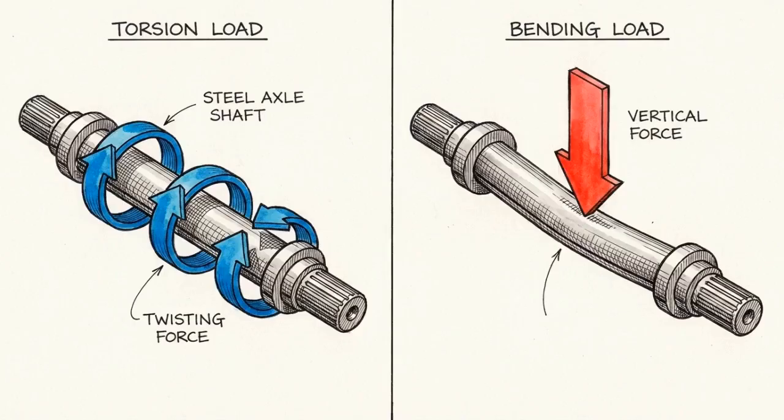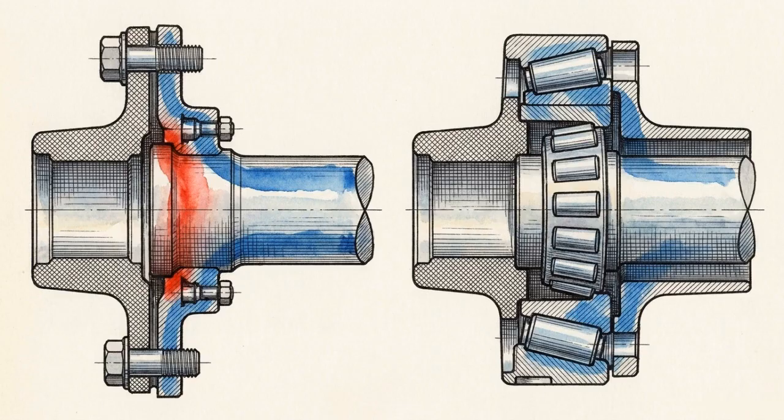The axle shafts must now carry this multiplied, balanced torque outward to the wheels, while the truck's 40,000-pound payload continues to push straight down. This cross-section details the semi-floating axle design common in light passenger trucks, where the wheel hub bolts directly to the end of the axle shaft. In commercial haulage, this exact architecture fails.